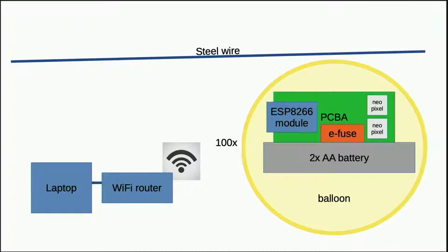So we designed a little circuit board. Here's the high-level system diagram I made at the bar last night. A bunch of 100 balloons in a 10 by 10 grid hanging from a wire. ESP8266 to connect to Wi-Fi, get packets with what the RGB value should be so I can control them all from my laptop. And then drive a couple of NeoPixels, powered by AAs, they last 12 hours, throw it in a big whitish balloon, hang them up, it works great.